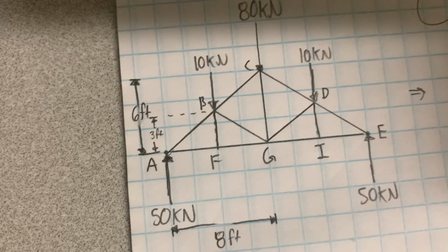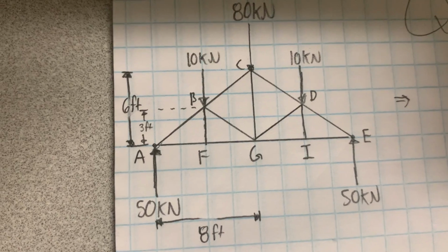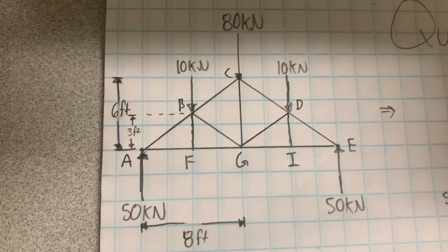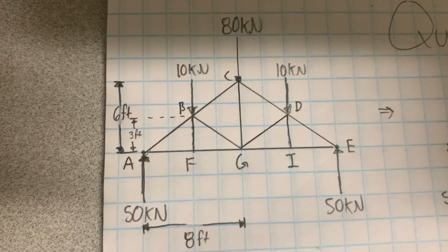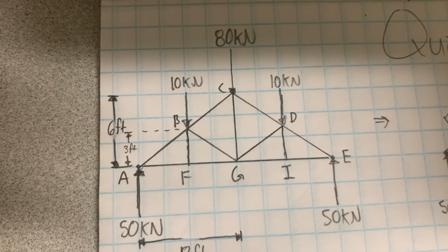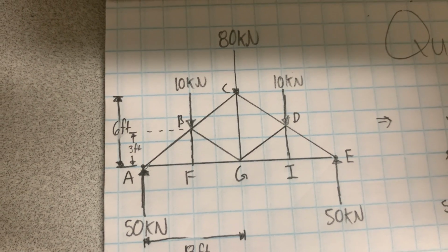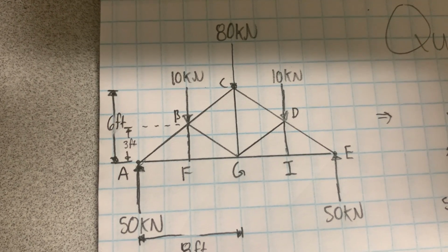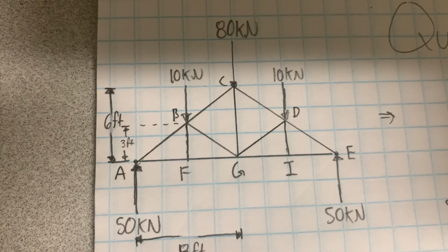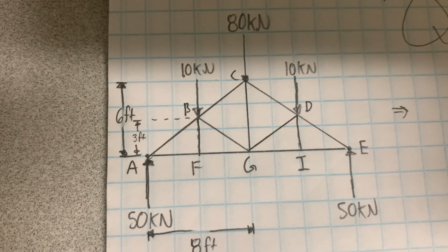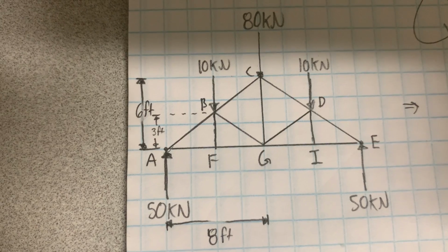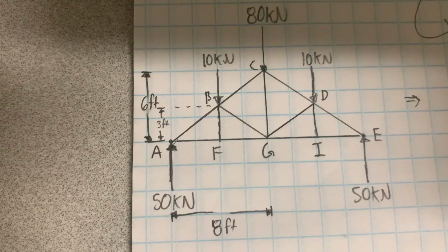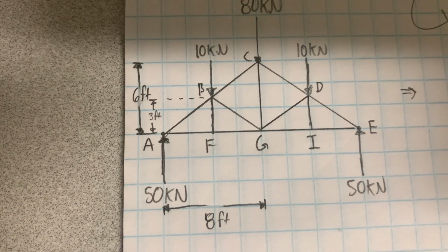So a machine contains moving parts, and they are designed to transmit input forces. In other words, it is an assembly of rigid and sturdy members capable of generating work. On the other hand, a truss is designed to support loads and consists entirely of two-force members. A frame is composed of beam members that are connected rigidly or by pins at joints. And in those cases, at least one member is a multi-force member. And a multi-force member supports three or more forces, or at least two forces and one or more couples.